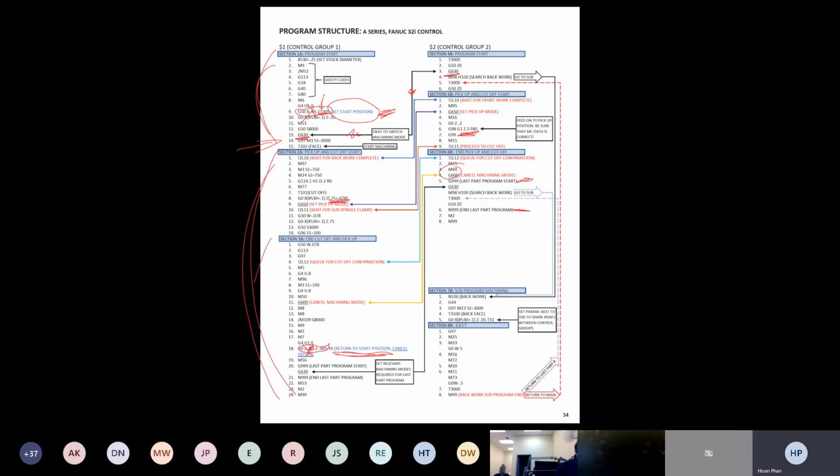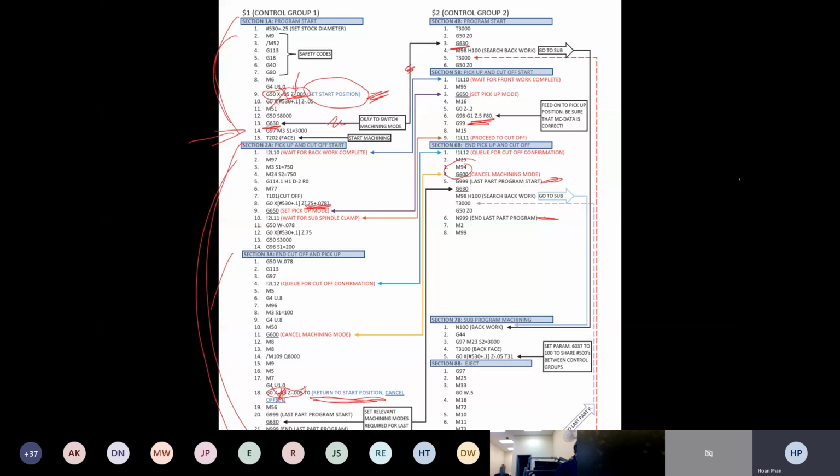On the Mitsubishi control, you can have M94 on either $1 or $2. The machine will take it and will not give you any problem or any alarm. But in Fanuc control for this A320 machine, you need to put the M94 in $2, and some other M codes are also like M34. You cannot put it on $1. If you do that, it will alarm out.